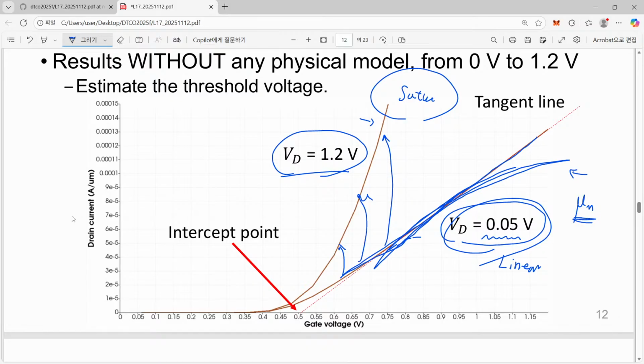Unfortunately, if we apply higher and higher gate voltage, it means that we wanted to get more and more electrons, and higher drain current. But unfortunately, there is a tendency toward reduced electron mobility when we apply higher gate voltage. So although we collect more electrons, their speed is reduced. That's the reason why we have a reduced slope in this case.